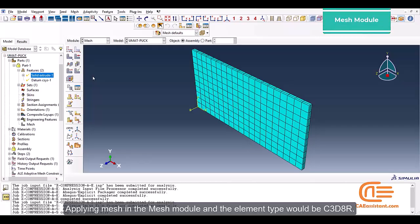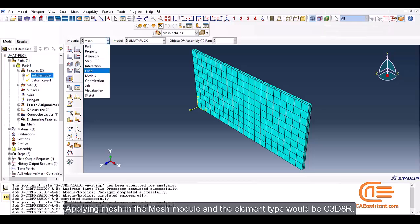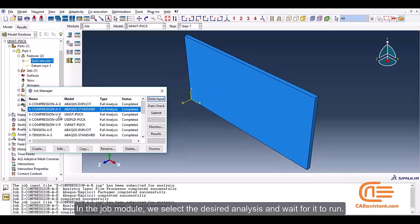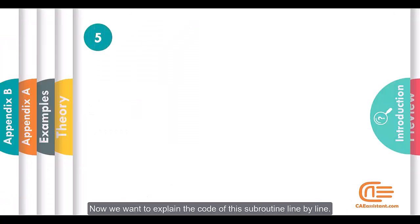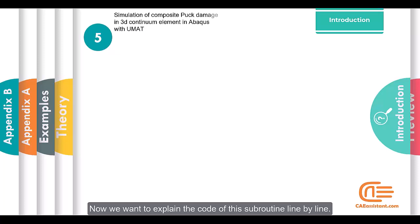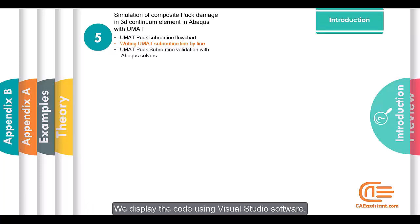Applying mesh in the mesh module, and the element type would be C3D8R. In the job module, we select the desired analysis and wait for it to run. Now we want to explain the code of this subroutine line by line. We display the code using Visual Studio software.